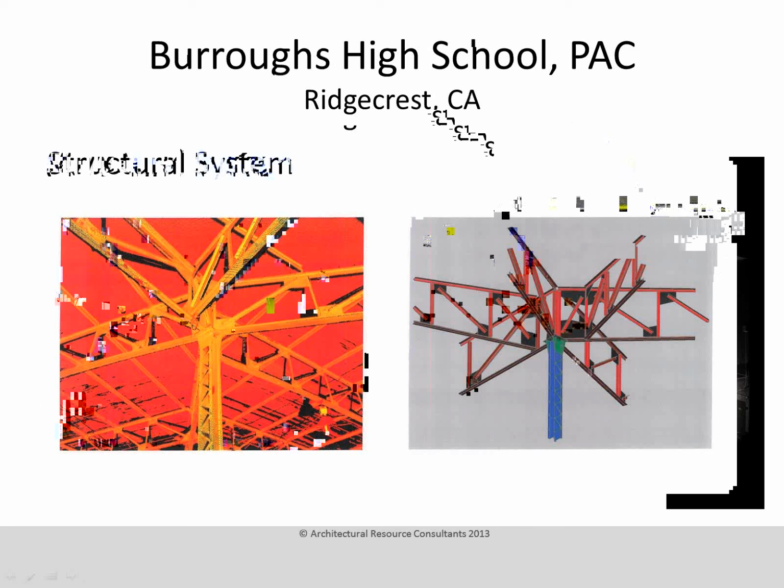And you can see the laser scan data here and how it fits to the bottom side of this truss. And there's actual camber built into the truss before it was fully loaded, and the scanner picks that up. So any real-world out-of-plumb conditions are going to show up in the scan data.